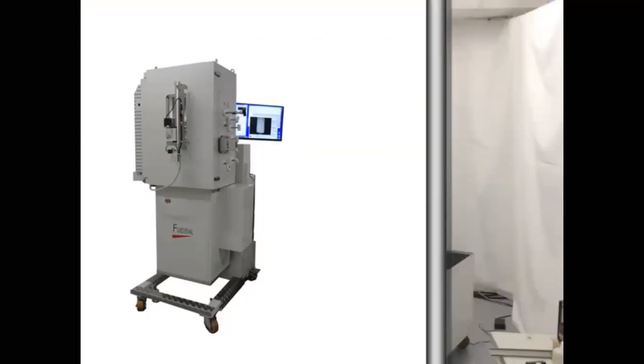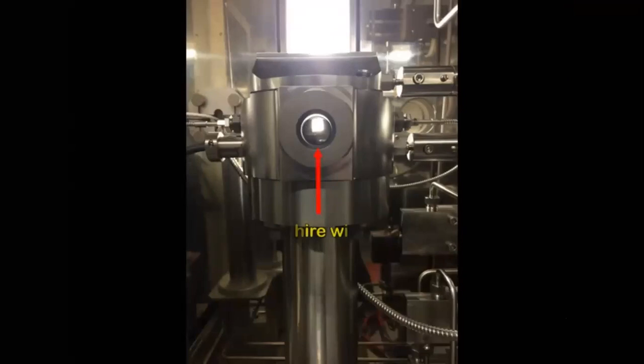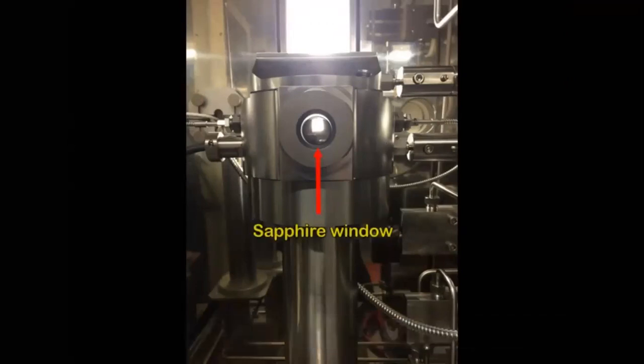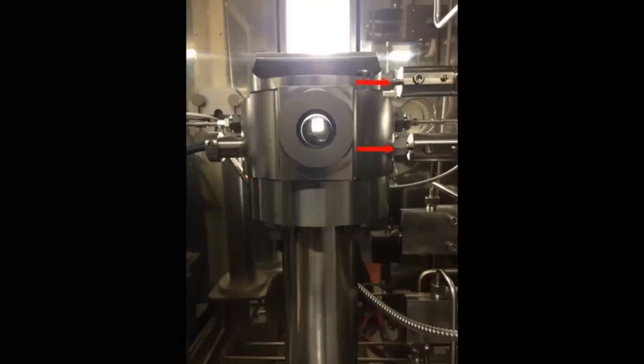The PVT cell and flow assurance modules are located and maintained in an isothermal air bath. The PVT cell is equipped with a sapphire window to visualize the gas-liquid interface during the PVT test. This is actually a high pressure chamber, where the fluid is inside it under high pressure, for example, 5,000 psi, 100 degrees centigrade. A temperature compensated pressure sensor with an accuracy of 0.02% full scale is mounted onto the PVT cell.